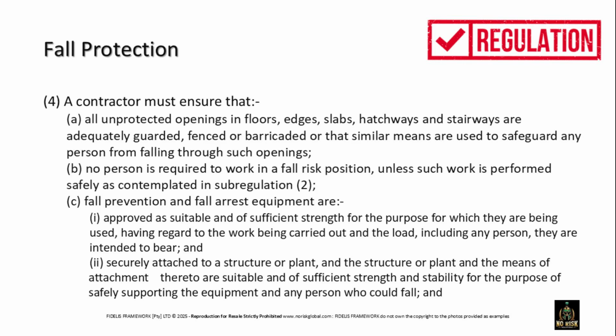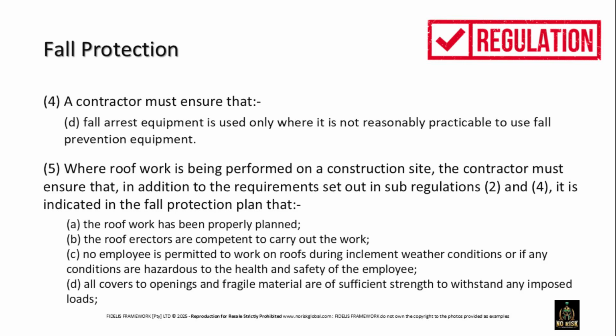Contractors must secure all unprotected openings and ensure fall prevention equipment is adequate and suitable for its intended purpose. This is crucial to prevent accidents and ensure safety on site. Fall arrest equipment should be used only when necessary. For roof work, additional precautions are required, including proper planning and ensuring employees are safe from hazardous conditions.